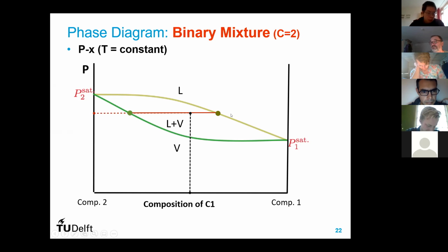Now, when you're in between, you need to compute the tie line. And this is the main idea, right? So geometrically, it's very straightforward. Numerically, if you just take the assumption of the K value as a function of pressure and temperature, it's also straightforward, not so complicated, right? At least you have already seen how to do it for simple K value, and with Xiaoming next time, I think, not today, you will look into some of these computations of the flash and stability test. That's it.